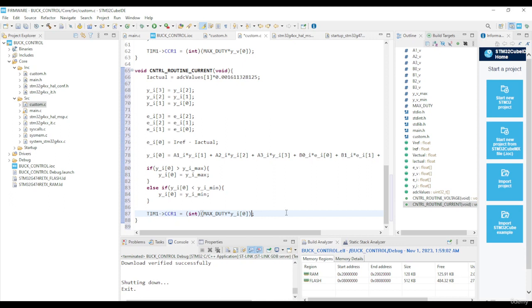So in these cases, it's better to utilize 1% resistors because they give much more accurate results. So you should utilize those instead of 5% resistors, and you would get much more accurate values. Changing the offsets in the code or changing it according to what I see on the output is sort of going to be a mess. I like to keep it nice and tidy, as with what I calculated. So in your applications, I encourage using 1% resistors for output voltage sensor applications. Yeah. All right. That's that, and the max duty stays the same.